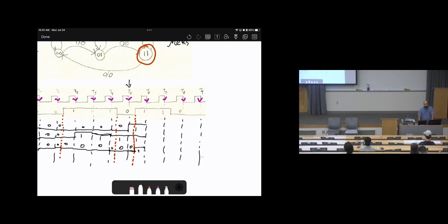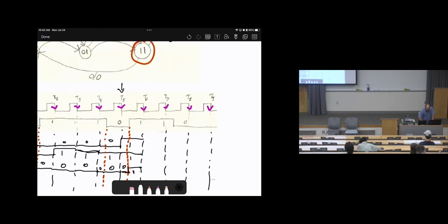Okay, do you agree with me? Because it is a mid-cycle change. Again, this is a Moore model. If it is a Moore model, don't worry about the change, because the output will be a function of states only. But now, the output is a function of states and inputs. So there is a mid-cycle change in the output. So now they are all 1s: 1, 1, 1.